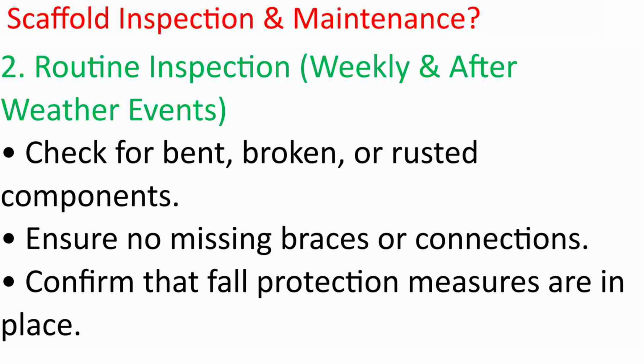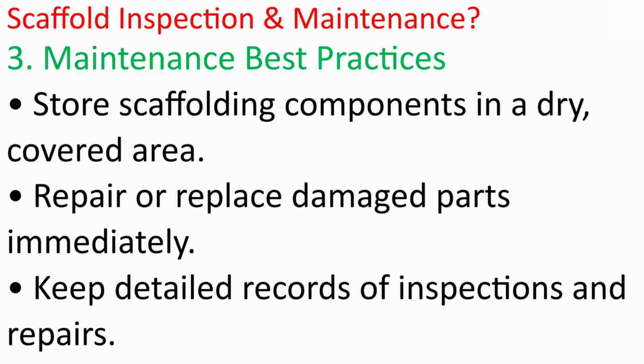2. Routine inspection, weekly, and after weather events. Check for bent, broken, or rusted components. Ensure no missing braces or connections. Confirm that fall protection measures are in place.